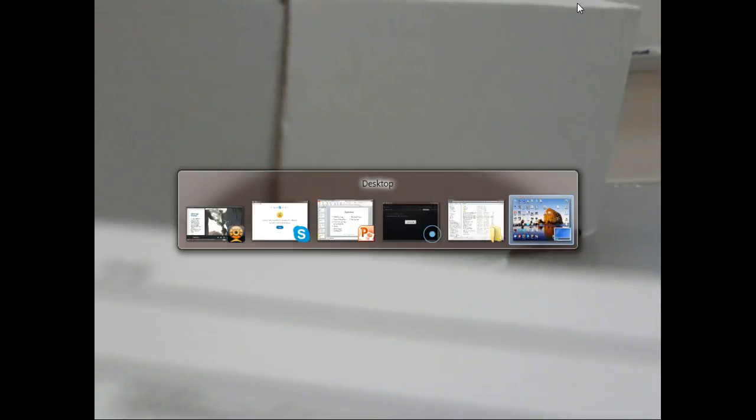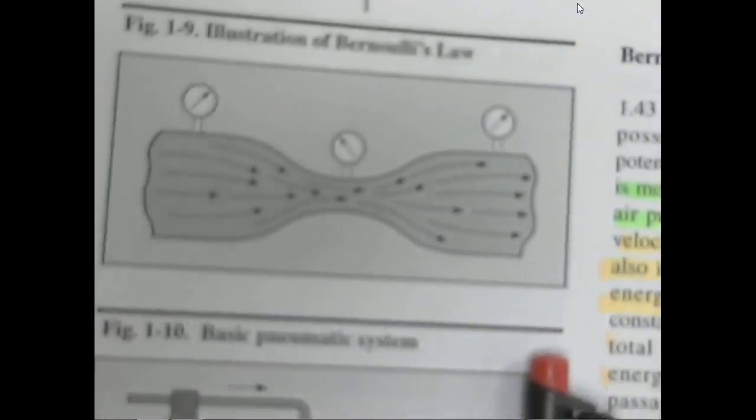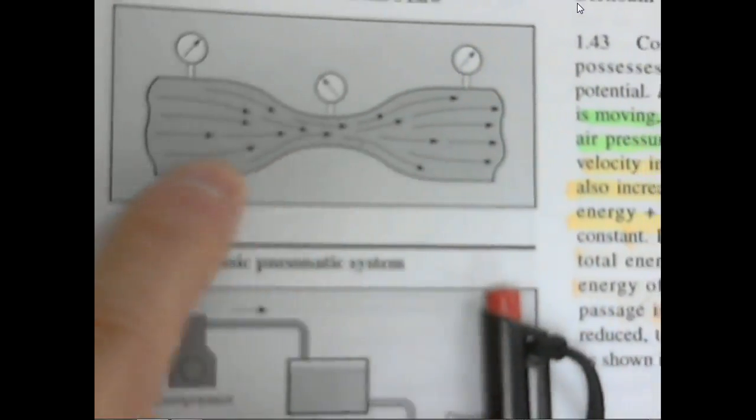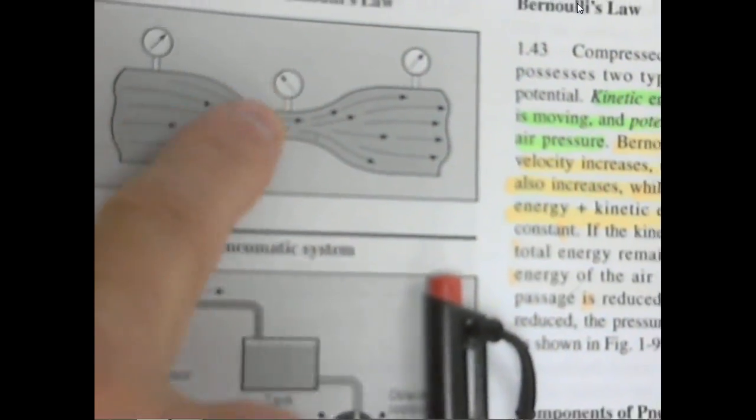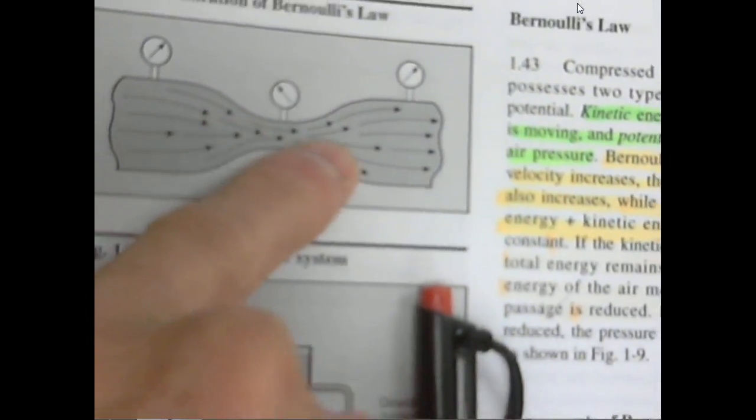Over there on the manufacturing line, we have a vacuum generator, but we create it from a pressure source. They do it exactly the way they show it in the book. This is the way a vacuum generator works: we bring in the flow here, then we run it through a Venturi, and then it expands back out.